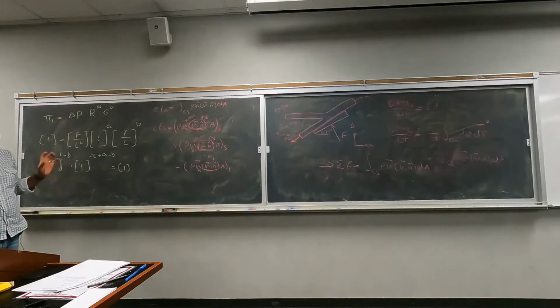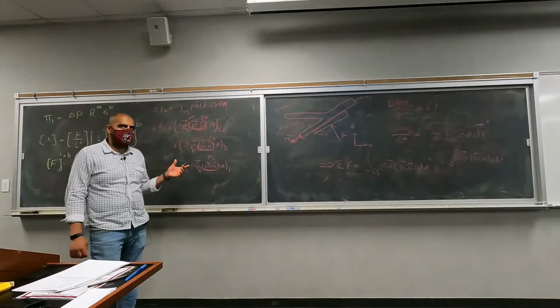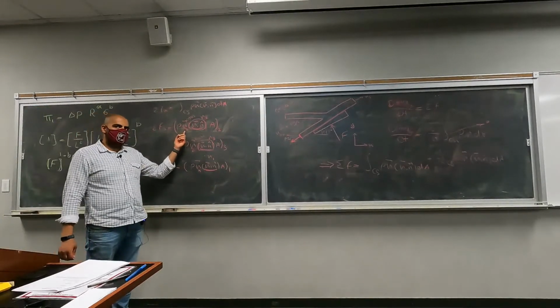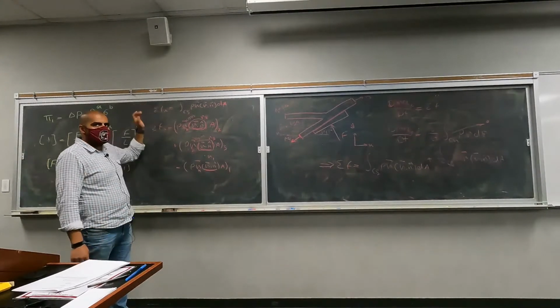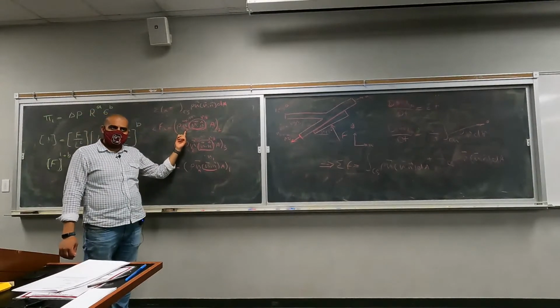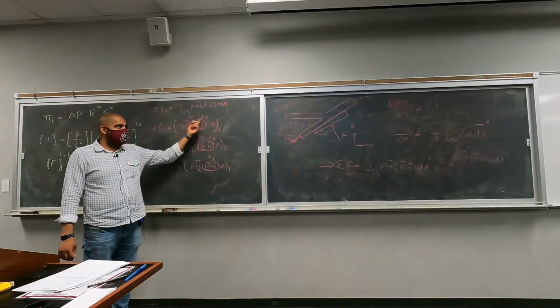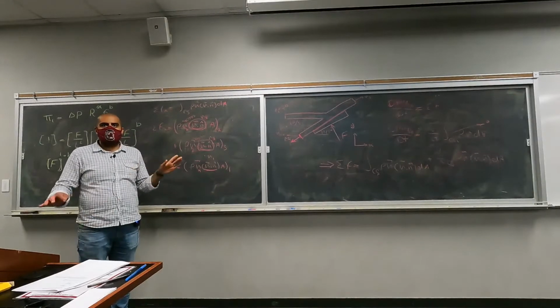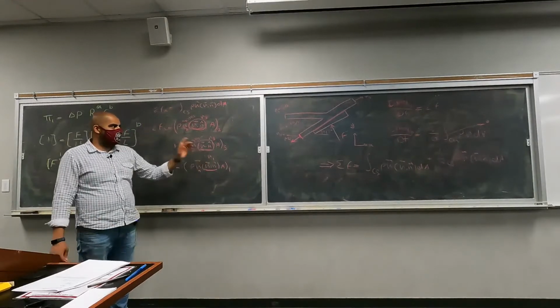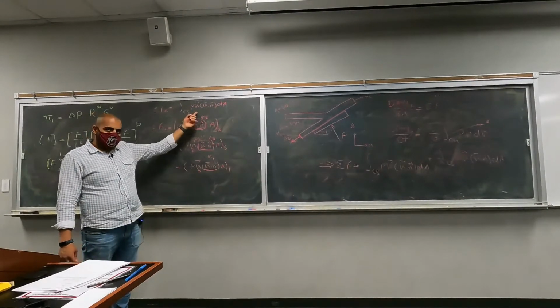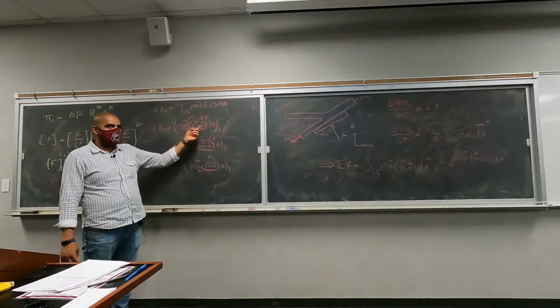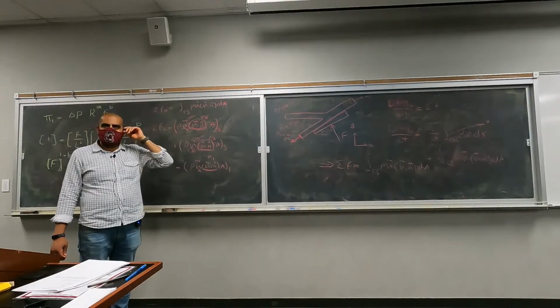The only thing that I really want you to focus on is this part: when you're writing the linear momentum, this is the velocity in the direction of this force, whatever direction that is. If it's Fx, this is the velocity in the x direction. This, though, is the velocity normal to the surface, whatever that velocity is. So if you write this equation for sigma Fy, here you're going to get v2 sine of 45, but v dot n is going to remain v2. Does this make sense?